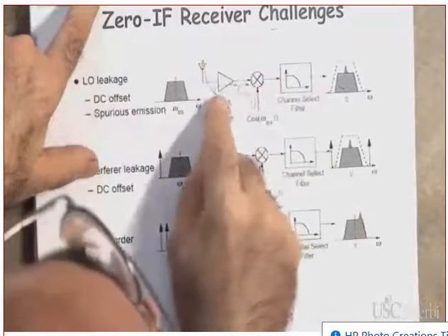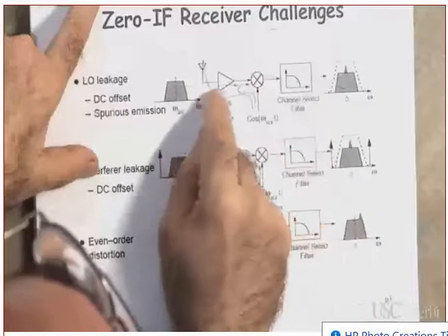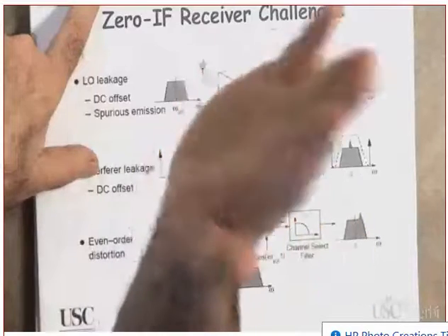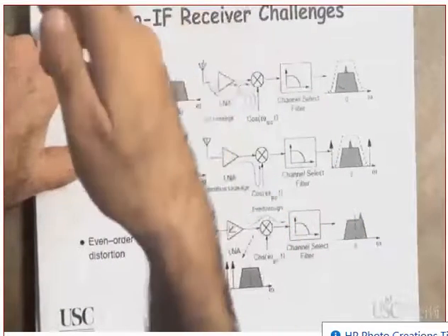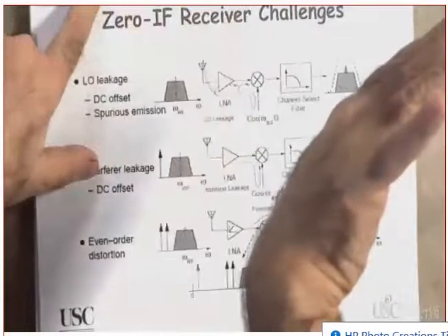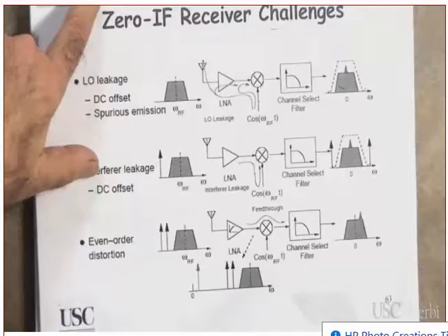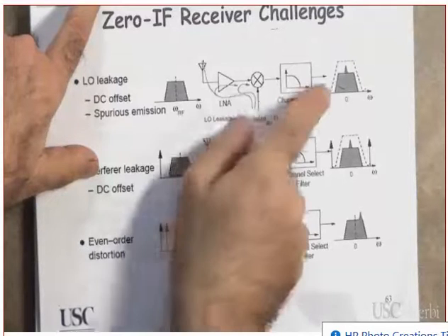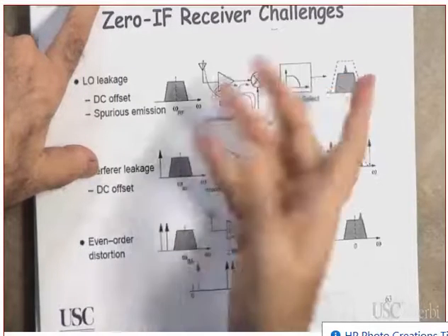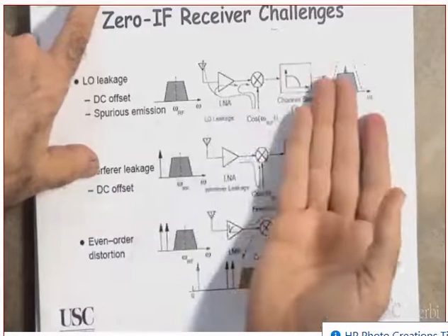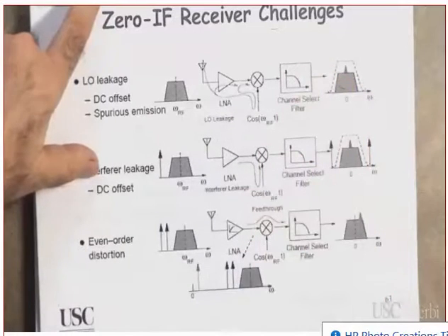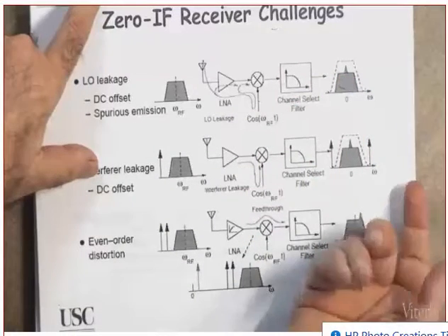Okay. But to do that, one possibility is to use a baseband spectrum not centered around 0, but a little bit away from 0, so that the DC offset will have no effect. Can I use a blocking capacitor to get rid of the DC? A blocking capacitor will take the band with it. Remember, a blocking capacitor means a high pass filter. Yes or no?